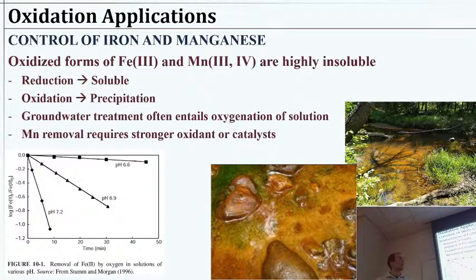As soon as we bump the pH down to only 6.6, we have made the solution more acidic, and that's changing the proclivity to oxidize, right? So it's much faster to oxidize at the higher pH, much slower at the lower pH, and therefore a small shift, but now we are removing the iron much more slowly.